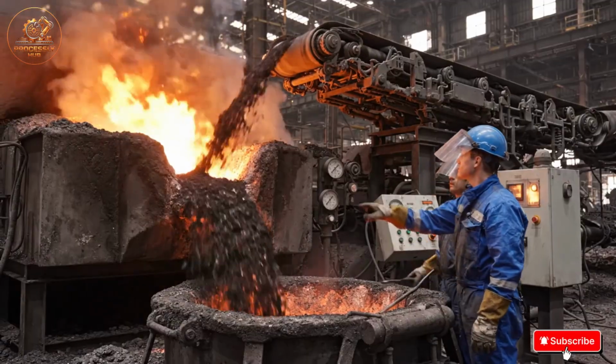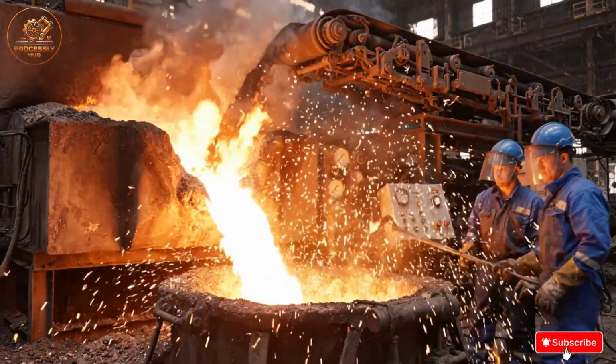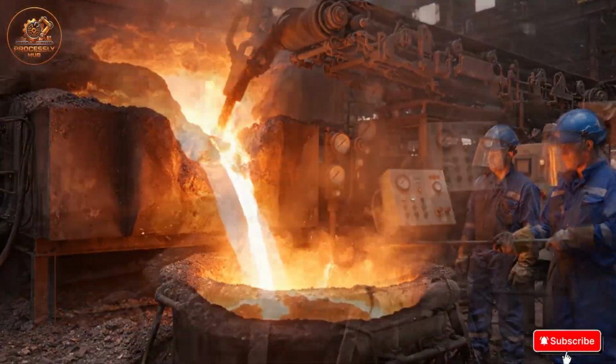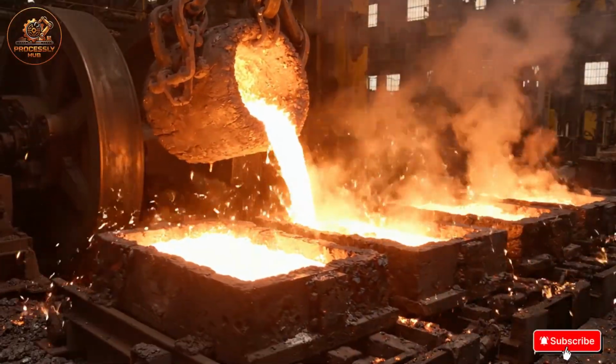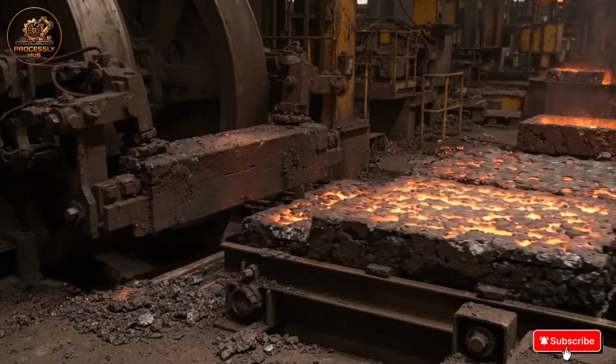The concentrate is smelted at extremely high temperatures. Sulfur and impurities are separated from the copper. Blister copper is cast into heavy anode plates. These plates are prepared for electrolytic refining.